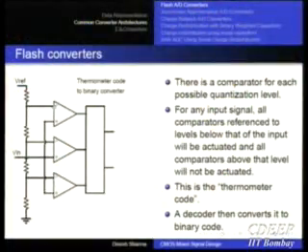Okay, the input sees all these comparators in parallel. So you are putting a huge capacitance on the input, and it is possible that the input driver, you may have a fast converter, but you can't charge the input to the value to be converted in the given amount of time. Okay, so this speed comes at a cost. Overall power is high, but also you can't go arbitrarily high in speed.